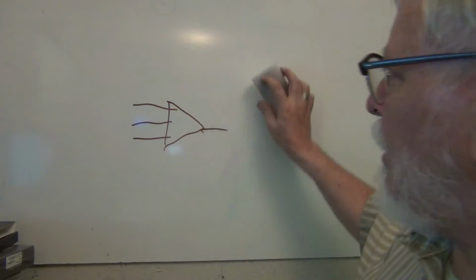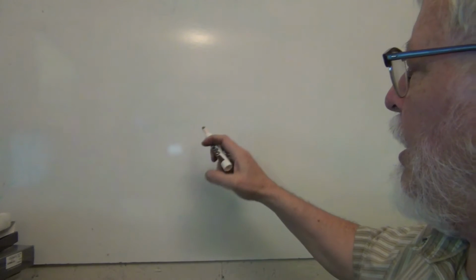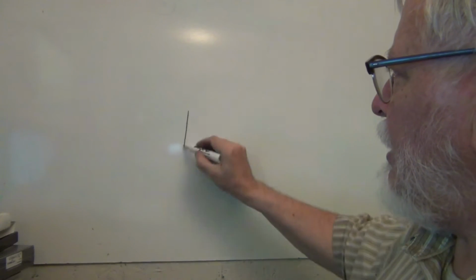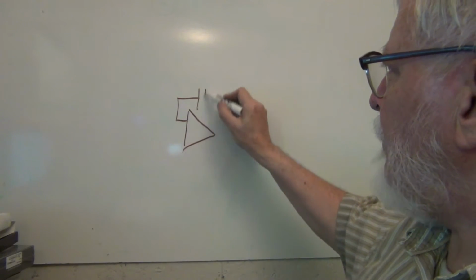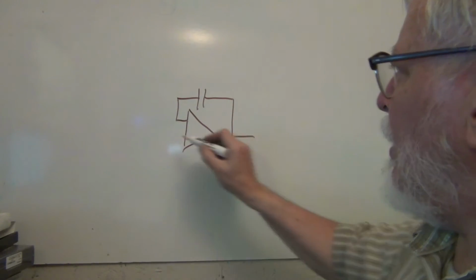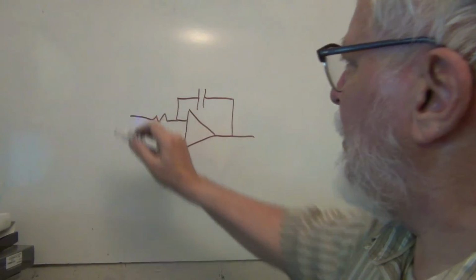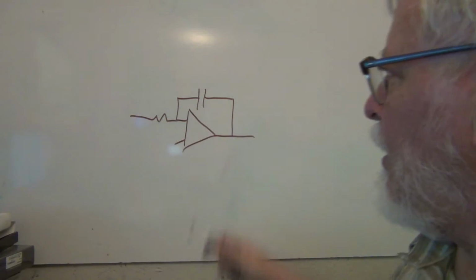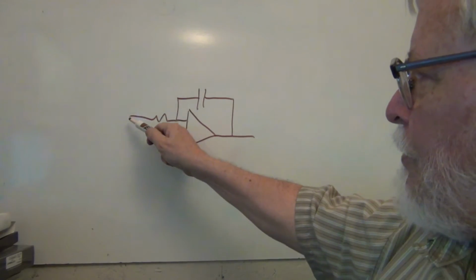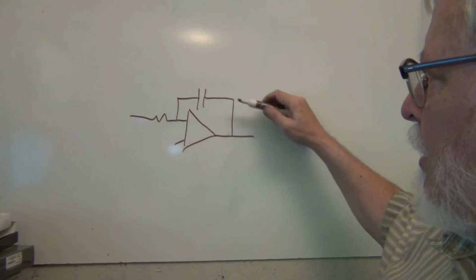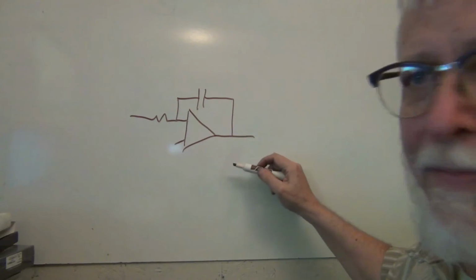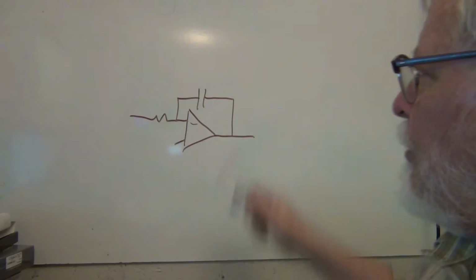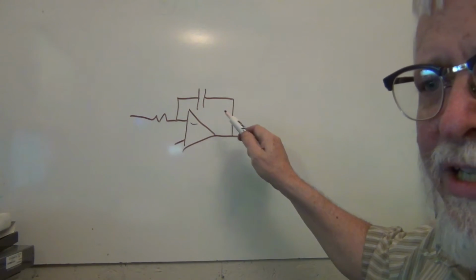All right. Now then, the next element that we run into is called a ramp generator, and in the electronics world, that works by having a capacitor across this input. So the way it works is, if you suddenly change this voltage, the amplifier tries to make its output move in the opposite direction, because that's the inverting input, but this capacitor is charged up and it doesn't let it.